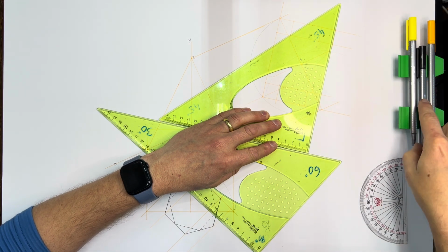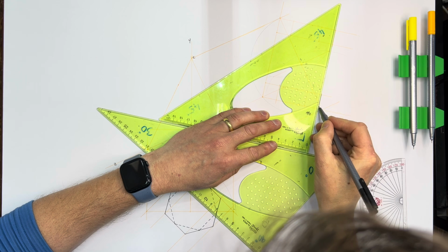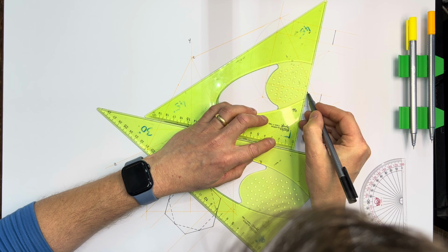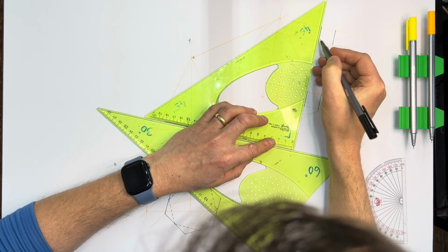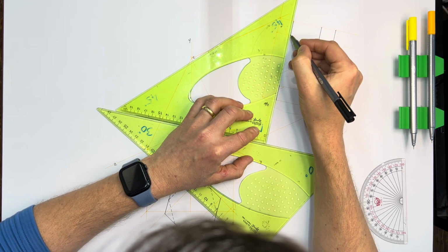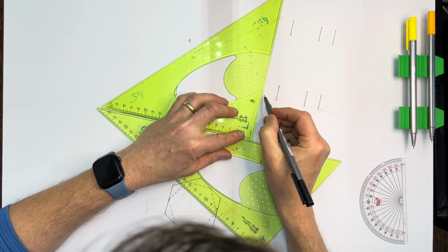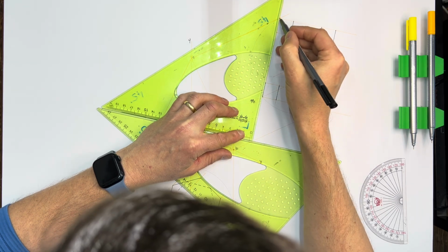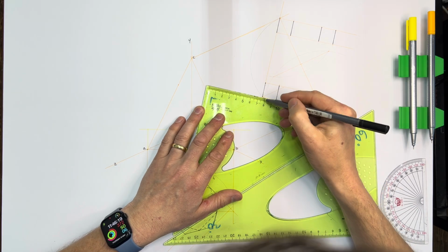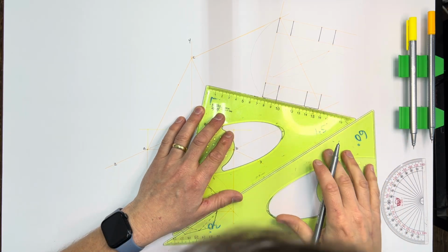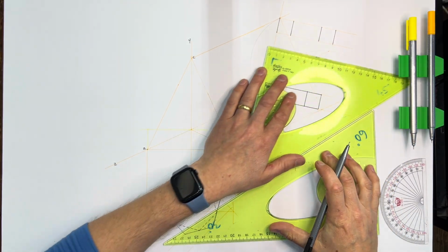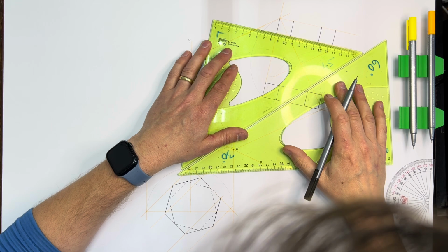And I'm just going to go one step further there actually and harden those in. Save me setting up the set square at a different time. Just do it all together. So there are immediate points that you can harden in your elevation. Okay, now this elevation looks slightly complex, but you'll see now that it's very doable.